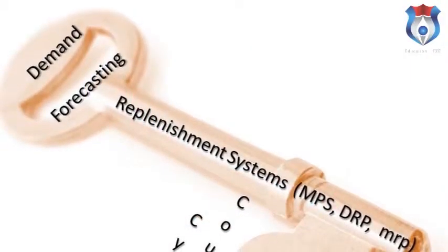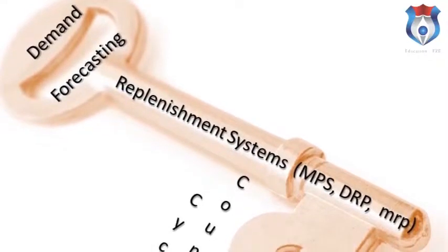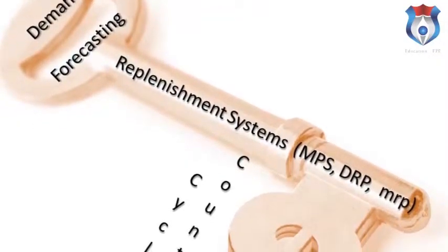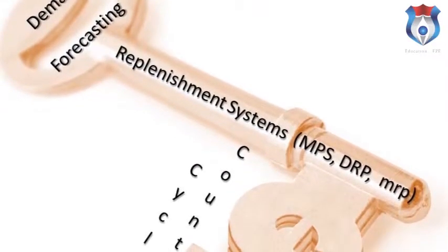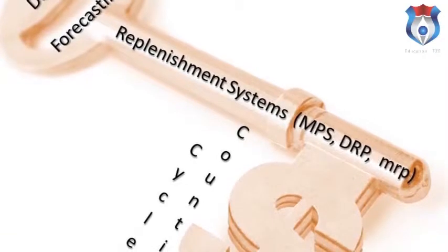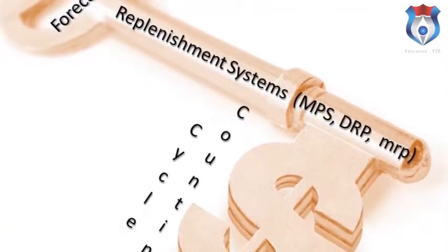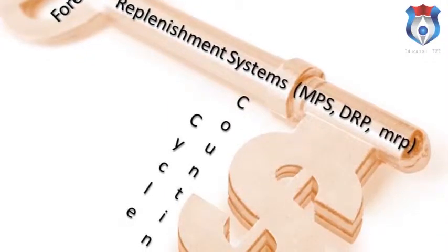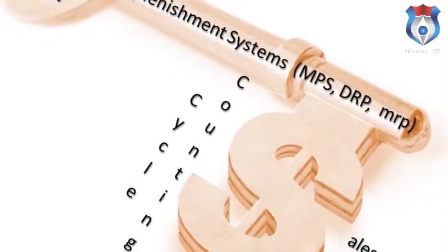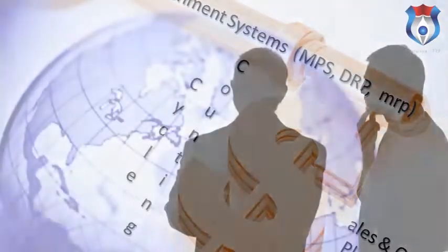For example, the commercial sector demand forecasting model contains the structure for estimating electricity demand for 9 types of buildings, 8 specific end users, and 3 fuel types, new and existing buildings, and for customers of publicly owned utilities and investor-owned utilities separately. This means that there are 960 components to the commercial sector demand forecast.